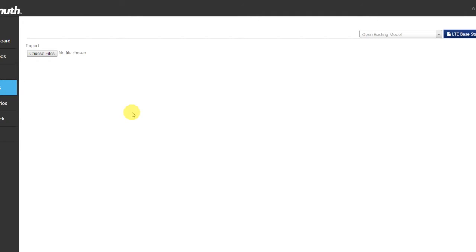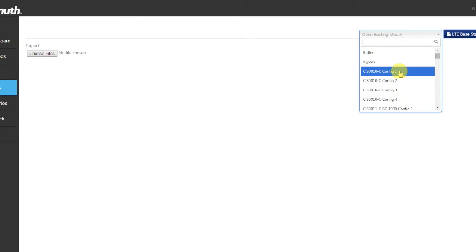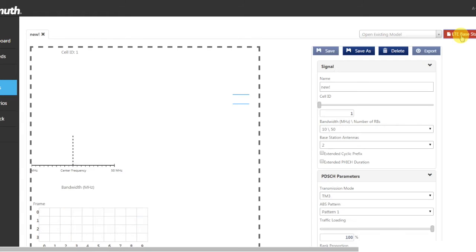So I guess you want to know how this works. Let's try to create an interfering eNodeB on Director 3, the software that controls both the RNX and VNE. On Director 3, we will start by creating our own LTE base station and then we'll play it back. To create the LTE base station, we have two options. We can modify an existing LTE base station or create a new one.